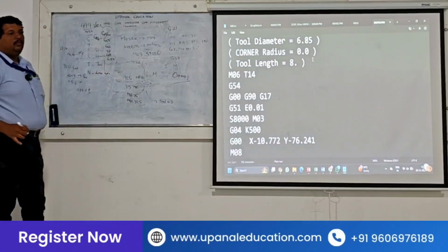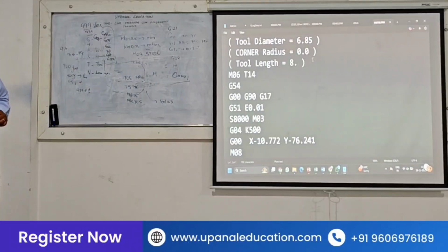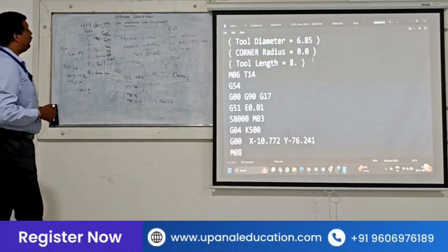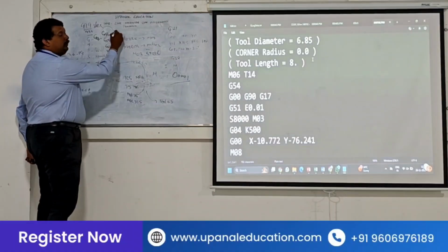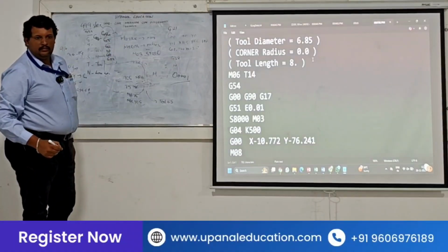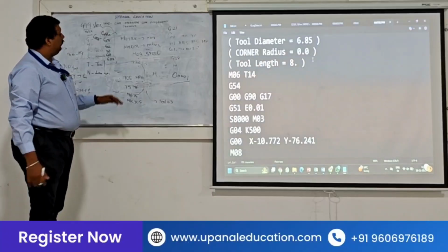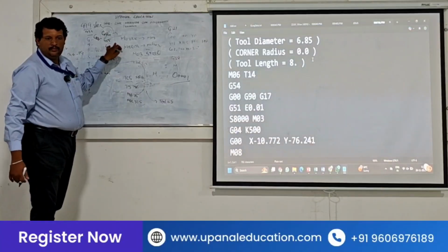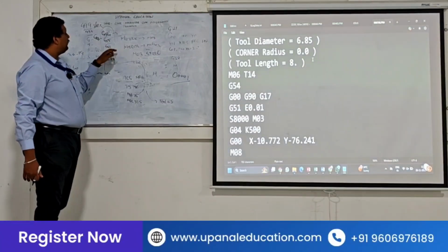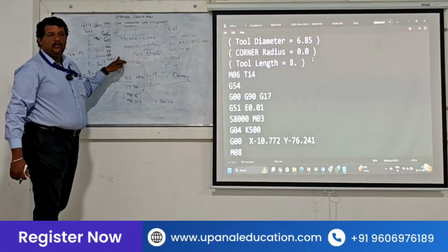These are work coordinates. Suppose we have 5 works. The first work we saved in G54. A second work has come. I saved it in G55. Okay. Next work in 56, 57.